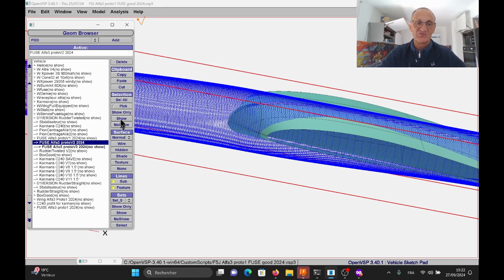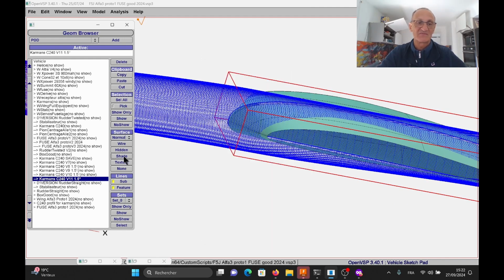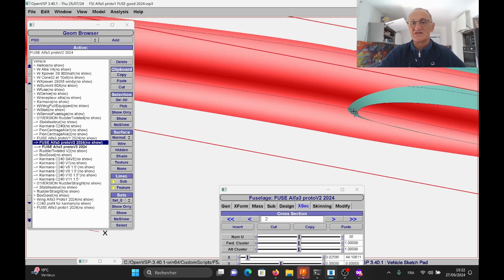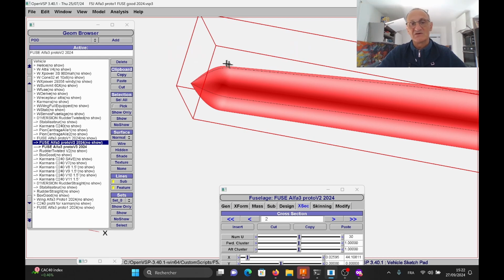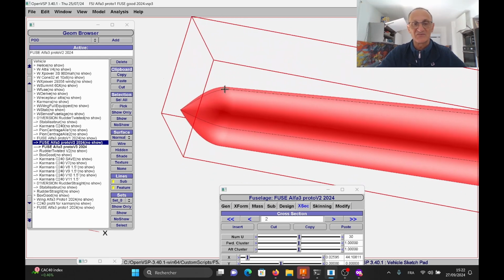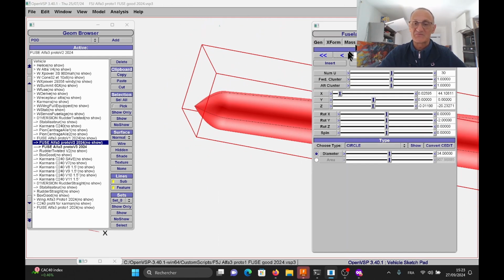What is going to help you tremendously if you have some problem of bad surfaces, something like this, in the region of high curvature, so here in the leading edge of this fairing, and also on top of the ending surface, the curvy surface, is that you could have some problems when you export this and import it into another CAD system.